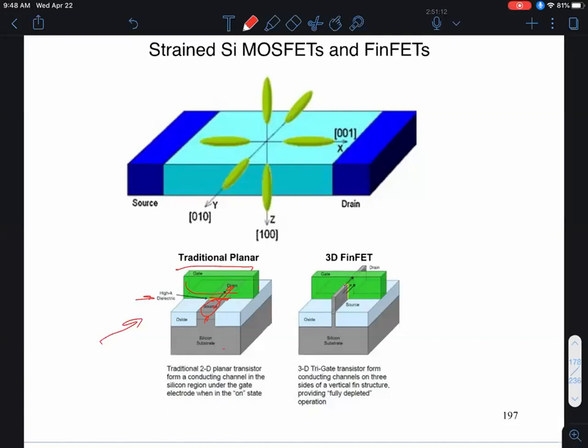Okay. The other thing that you see is surrounding this transistor, which has a length equal to that dimension. So that's my length of the transistor. That is the width of the transistor. But surrounding this transistor, I have what's called a field oxide. So that's an isolation or field oxide. And this actually surrounds the transistor on this side also. So it surrounds it on all four sides. And that's what makes this transistor not leak current to maybe another transistor, which might be located over here, or another transistor over here, another transistor over here, and all that.